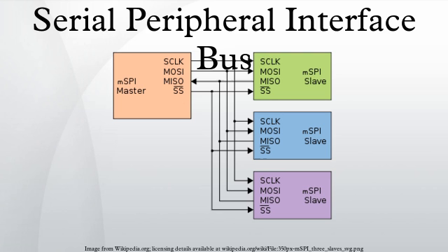Independent slave SPI configuration. In the independent slave configuration, there is an independent chip select line for each slave. This is the way SPI is normally used. Since the MISO pins of the slaves are connected together, they are required to be tri-state pins.